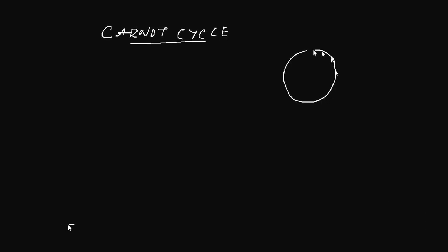We have discussed the Carnot cycle and reversibility in the previous video. So it was the Carnot cycle we discussed in the last video. A cyclic heat engine operating on the Carnot cycle can be termed a Carnot heat engine. If you have a cycle operating completely on the Carnot cycle, then you can call this engine a Carnot heat engine. Because all the processes in the Carnot cycle are reversible, the Carnot heat engine will be completely reversible.